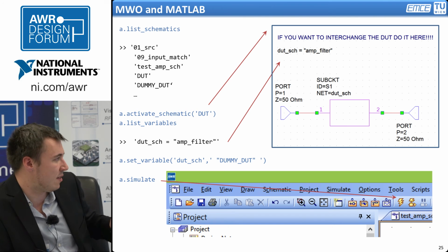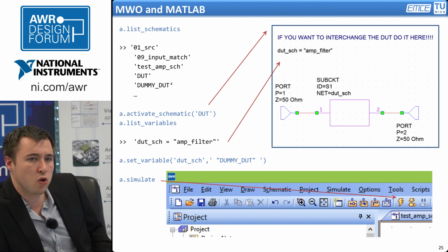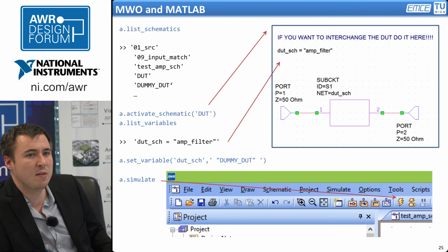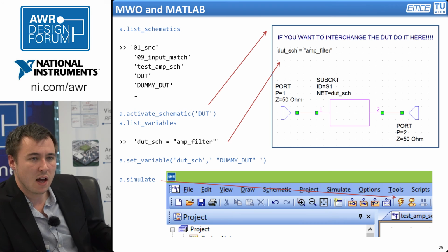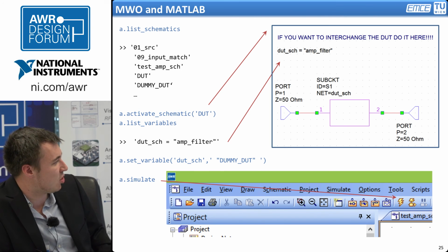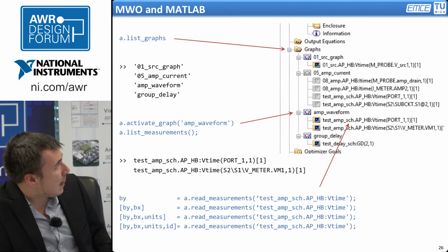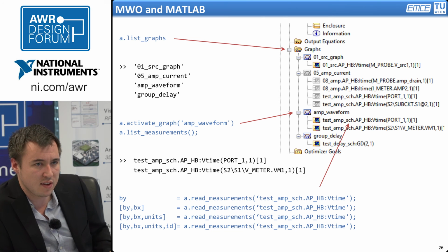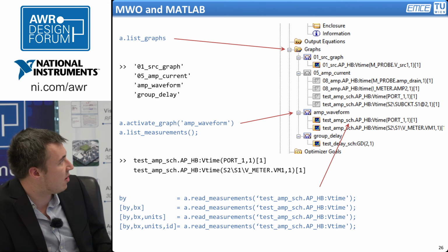And this is, I would say, a bit more convenient to use with arbitrary Microwave Office files than the way Visual Basic often handles it by just addressing it using numbers, which can be cumbersome, especially when the project gets changed or gets larger. And then you have the simulation command, which is the very same as clicking on the simulation button, and of course addressing the results of the simulation is now something very similar.